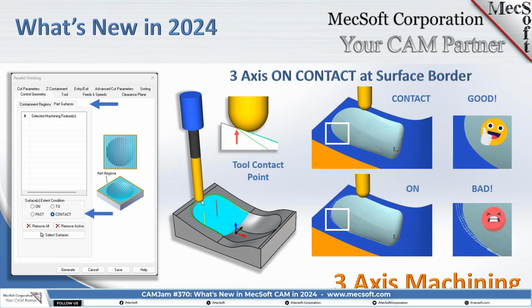The to condition: when the diameter of the tool touched, vertically lined up with any point on your profile, it would stop. And then the past condition: the diameter would go past the control geometry, and if you look at it vertically, the opposite side of the tool on the outside of the control geometry curve would stop.